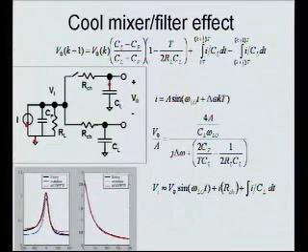What kind of selectivity do you achieve by that stuff? Basically, the bandwidth is set predominantly by the ratio of your load capacitor to your parasitic capacitor. So, to be more precise, actually, it's right here. This is the bandwidth. This is your offset frequency. So the bandwidth in terms of that offset from the LO is just proportional to this. So proportional to the period of your LO. That's what the T is. The ratio of the parasitic capacitor to the load capacitor, and then some extra R effects that usually don't matter very much. So it's basically just proportional to LO and to your capacitor ratio. So it means that it really is important to make the parasitic capacitance small.